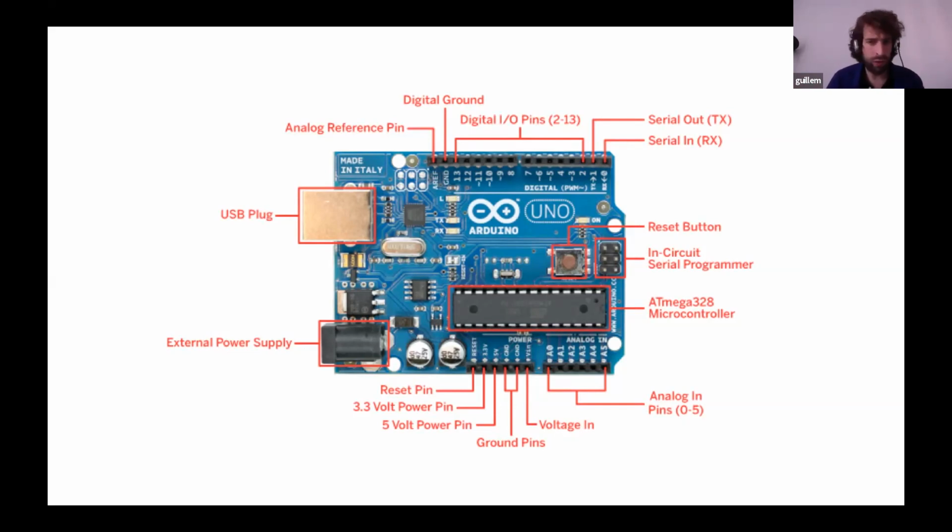And just to finalize this chapter on bootloaders, I think nowadays a really common type of bootloader is what's called OTA, over-the-air bootloaders. That's a bootloader that you might find inside home appliances that connect to the internet, like an Alexa device, a Sonos speaker, or maybe your ESP32, which allows a processor to download a file from the internet, which is a new piece of code, download it, reboot itself, and then boot from the new piece of code it just downloaded. So in a way, do a full software update. So as you see, bootloaders have a long life. They're not something from the past.